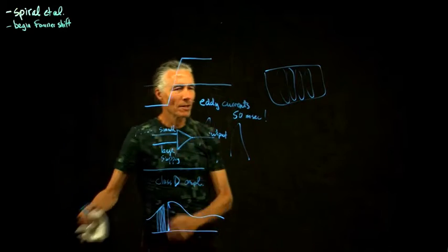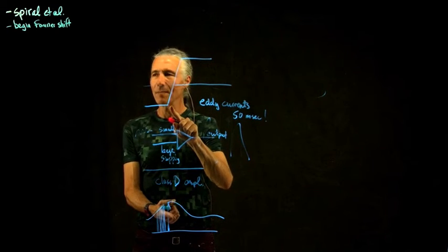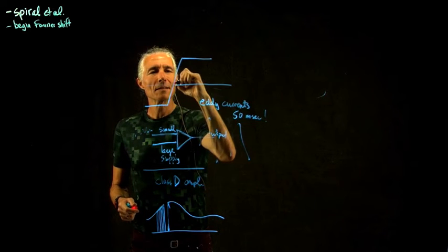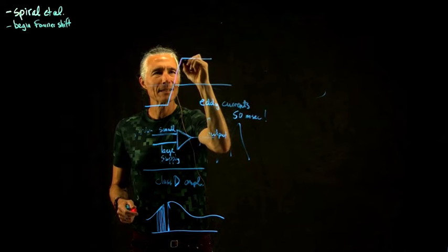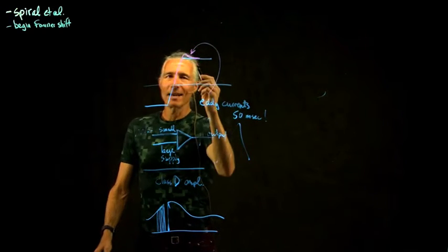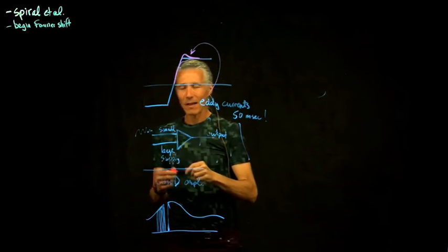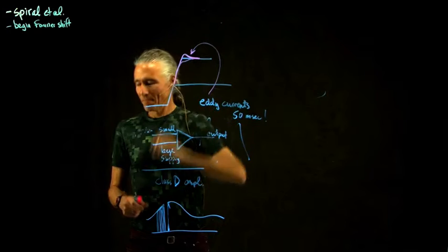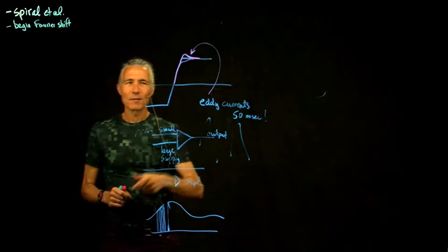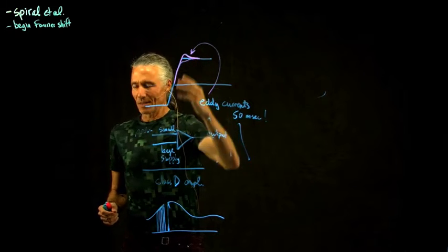And so it turns out if you do something like this, what actually happens, if I feed this signal into the amplifier, and the amplifier accurately generates a current that looks like that, the current will be going up like this, and then I'll make it flat, but instead it'll do something like that because of the eddy currents. So if you want to get something that actually looks like that, you need to feed in something that is more like that. And then what will actually come out after the eddy currents do their thing is what you want. So there's a whole calibration of the scanner for eddy current compensation that will translate what you said, what you want, into what you need to actually get what you want given the eddy currents.